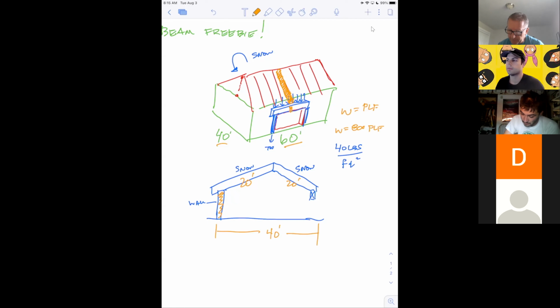Again, I'm just showing you this out of interest because it's kind of cool. And so let's say this garage door that you put in here was 16 feet long. And so does it make sense you have a 16-foot beam? So that means L equals 16 feet. And we know that W equals 800 pounds per lineal foot. Like that's 2 of the numbers we needed yesterday, right? And then we also need E and we need I.